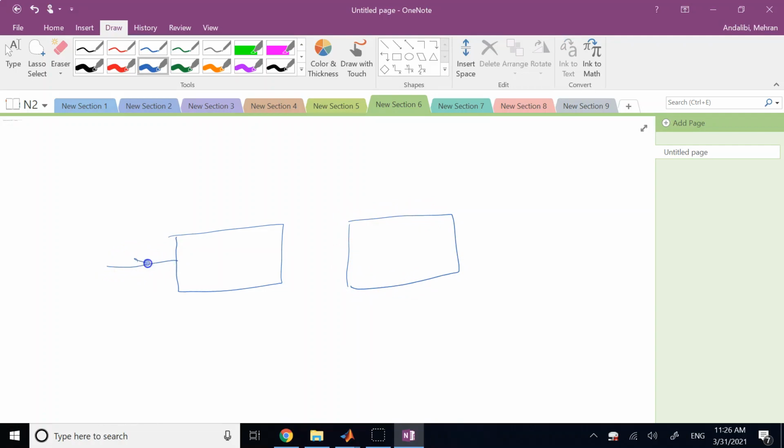The electrical part, you pass to it a voltage, and then it has basically this current that goes in, and then this current is transferred into torque, where torque is a constant times the current. And then this torque that is applied to the motor shaft is going to give you the angle or angular velocity of the shaft, like let's say omega. So this is the mechanical subsystem for the motor.